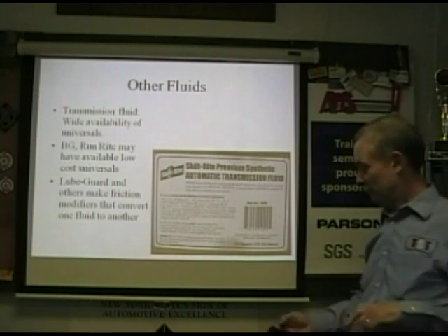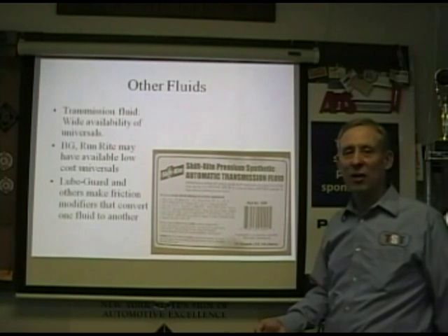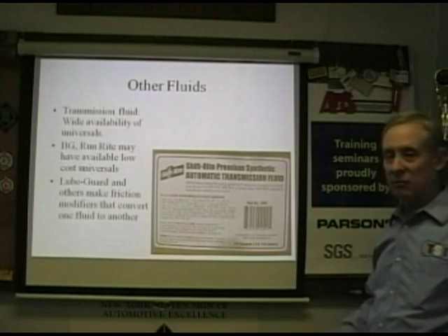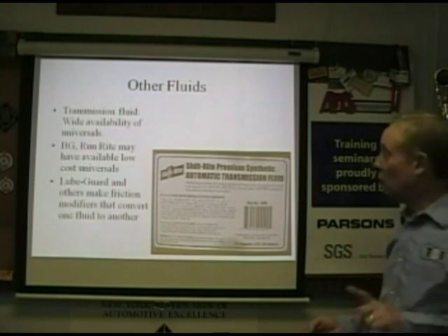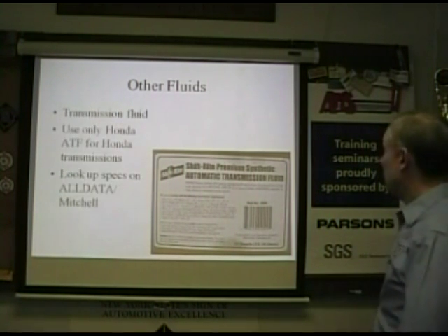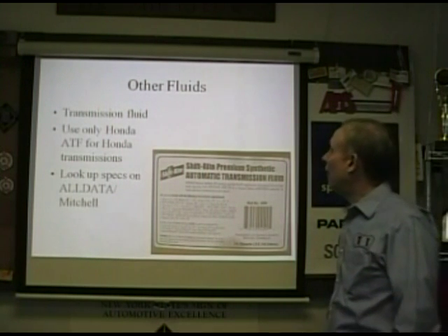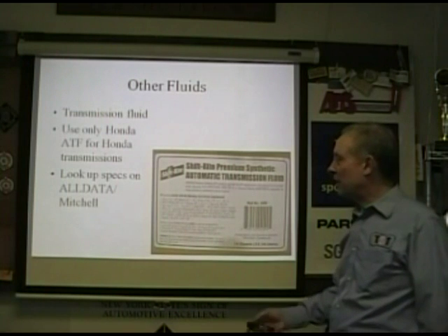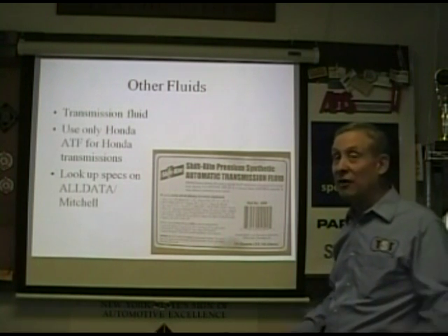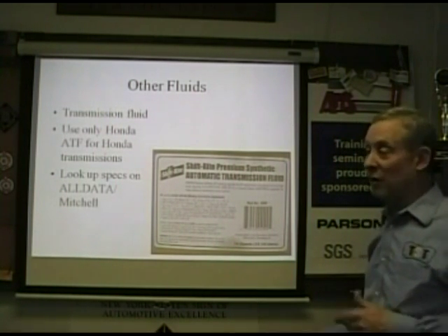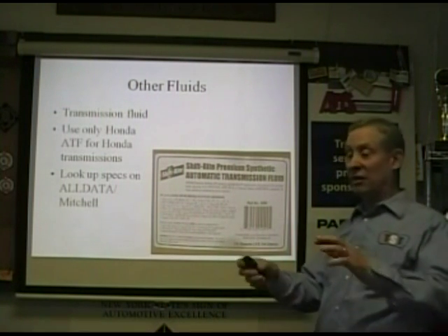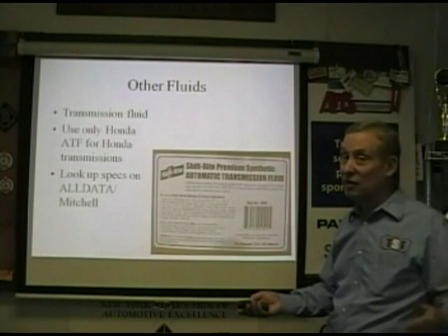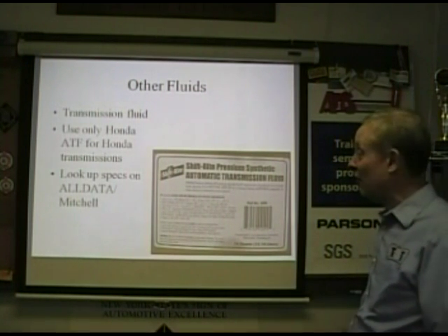Someone like Wayne Colonna at ATSG will tell you, they know it well. Use the correct LubeGuard by using their chart, with the correct fluid, and it'll work great. But be careful. Use only Honda ATF for Honda. Look up the specs and all data in Mitchell, or if you want factory information, you can go to nastf.org and get the factory links to all the factory websites, and you can get all the specs from the factories. They have a lot of stuff published.